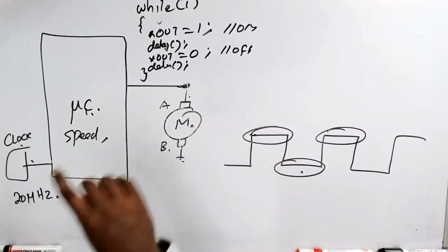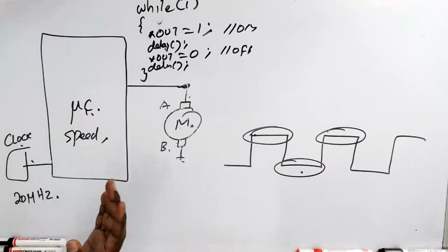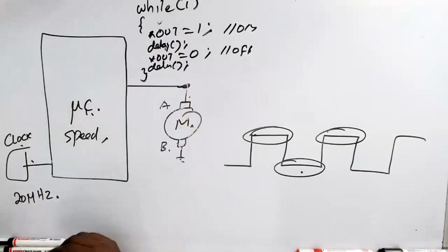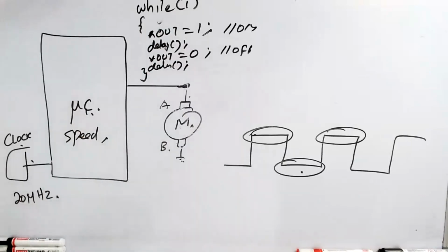Then this instruction will produce some delay. How do you find the delay? Unfortunately, there is no big calculation at all. Because you're writing the code in C, when it gets compiled to assembly language, you don't know how many instructions it generates. It depends on how good the compiler is. There are so many variables. Since you don't know the code, you have to do trial and error.